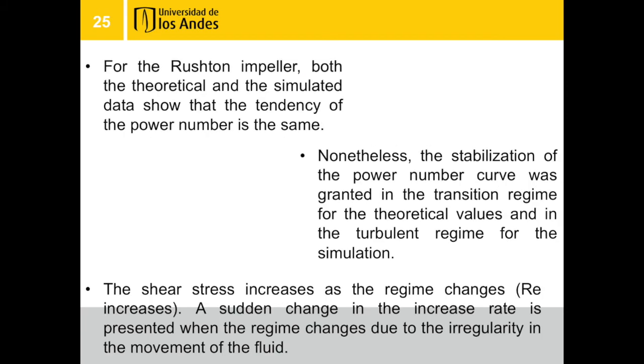For the Rushton impeller, both the theoretical and the simulated data show that the tendency of the power number is the same. Nonetheless, the stabilization of the power number curve was reached in the transition regime for the theoretical values and in the turbulent regime for the simulation.